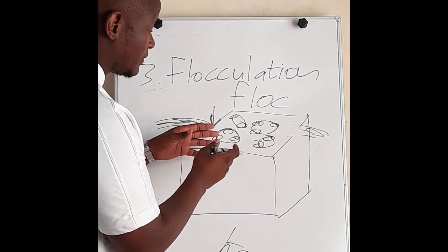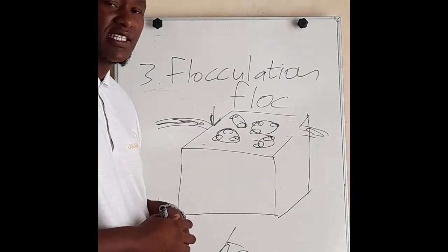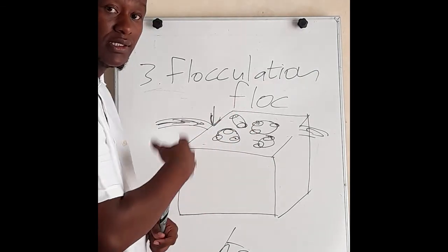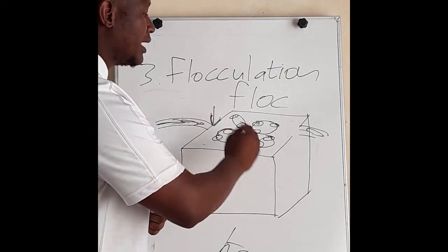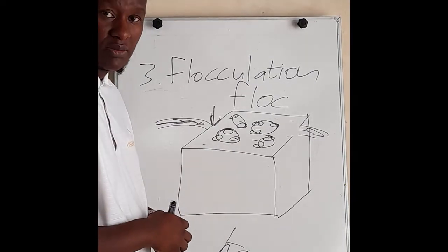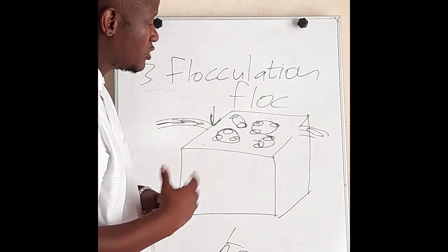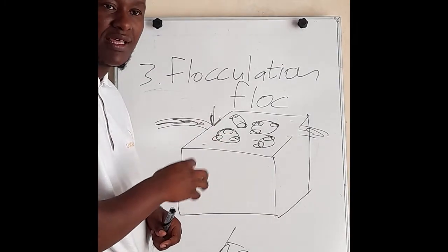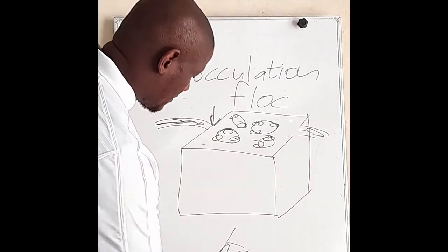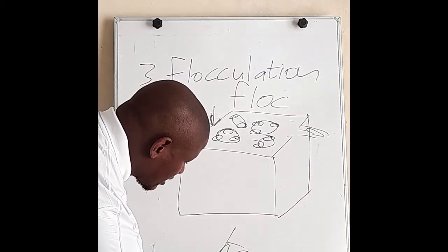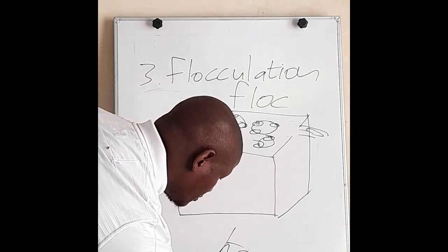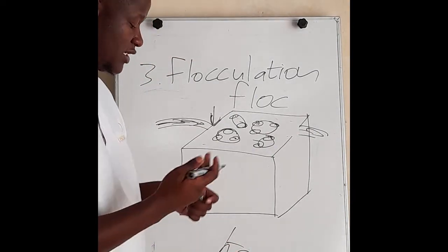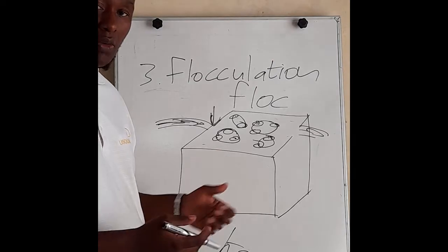By so doing, we'll then see under sedimentation what advantages that does for us in terms of trying to clear out this water from solid particles that are in suspension. Because we should also remember, the more particles we have in suspension, the higher the turbidity is. Turbidity basically also affects the color of water. Turbidity is just made up of suspended solids in our body of water.